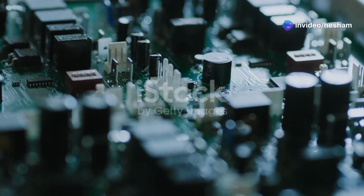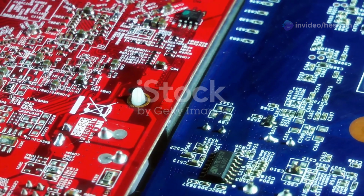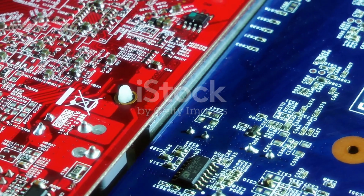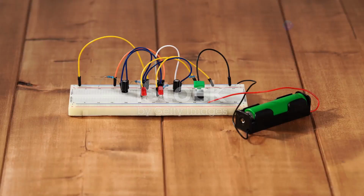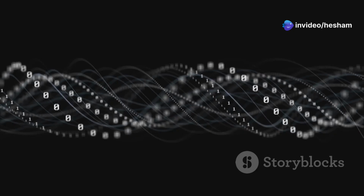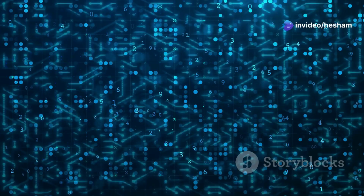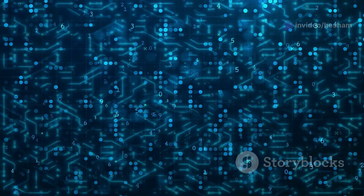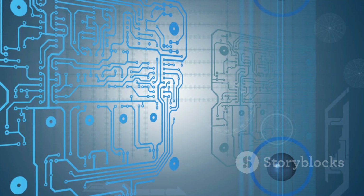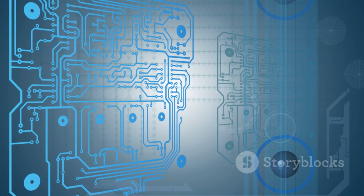Now let's talk about arithmetic. Adders and subtractors are essential combinational logic circuits that, you guessed it, perform addition and subtraction. The most basic adder is the half adder. It adds two single-bit binary numbers. A full adder, on the other hand, can add 3 bits, 2 input bits and a carry bit from a previous addition. These adders are the foundation for more complex arithmetic circuits.